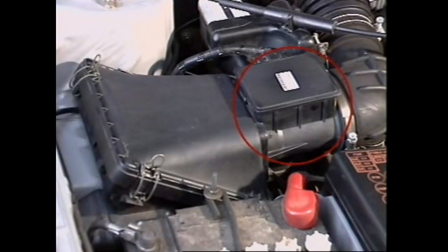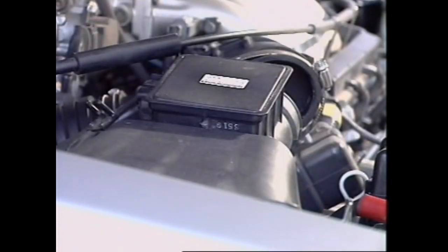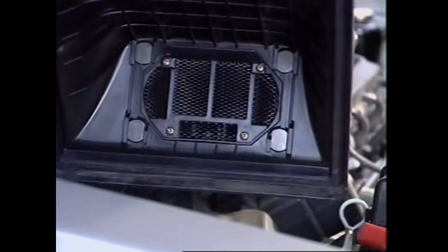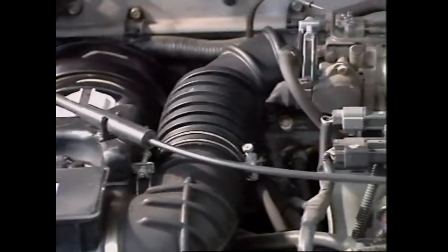An airflow meter measures the volume of filtered air entering the engine. It can be mounted on the air filter casing or close by. All air entering the intake flows through the meter, then through a sealed flexible hose or duct to the throttle body, then enters the engine.